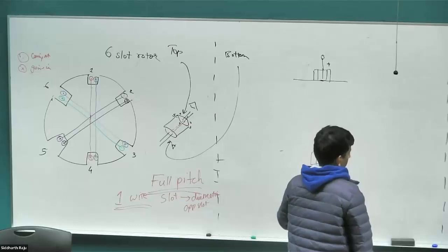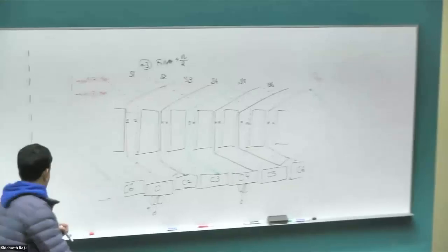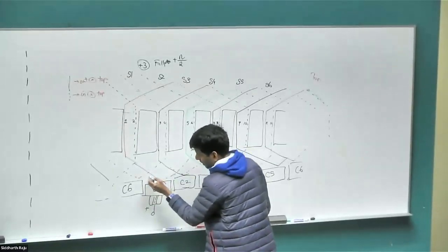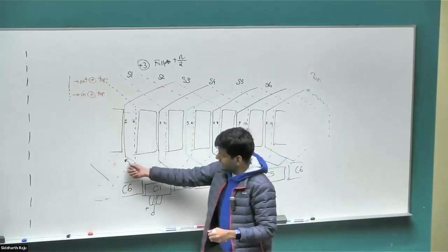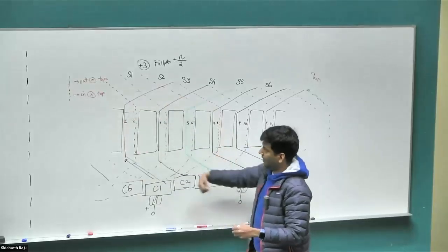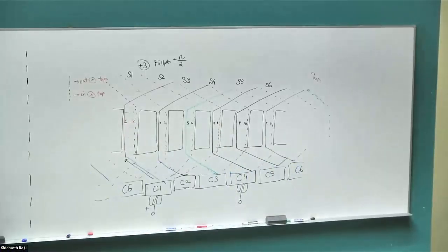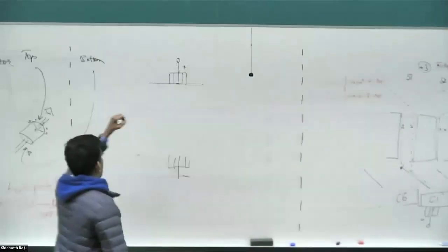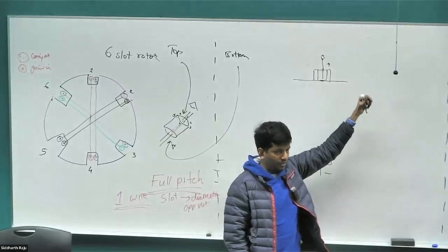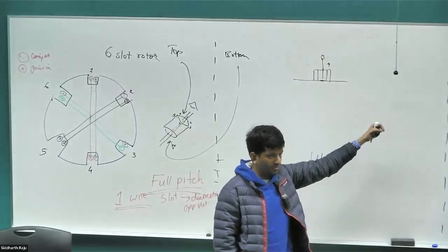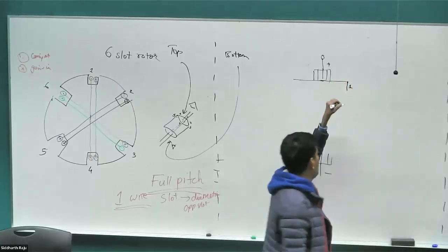Once we are at the positive terminal, it splits into two pathways. So let's trace out this set of conductors going this direction, and then we'll do the same thing for the other direction as well. Starting from here, just trace out the wire that I've drawn and give me the numbers for the conductors alone. Can somebody tell me what the first conductor would be? What's the number for the first conductor coming out of the commutator that I've chosen? 1. And then it goes to conductor 8.